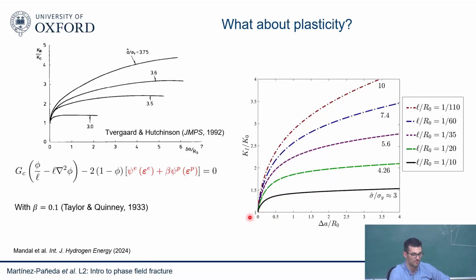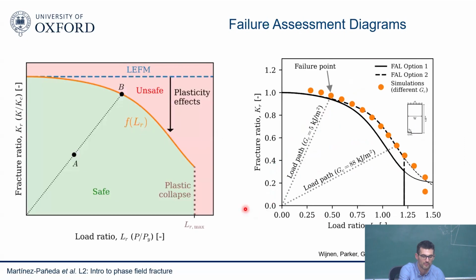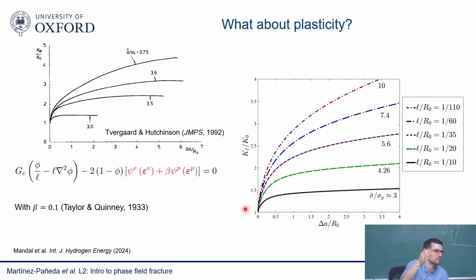Cracking starts always at the same place. You know your fracture toughness. So the only thing that you don't know is how much plastic dissipation you have. And that will depend, of course, on your yield stress and your strain hardening exponent, but those things you know from a uniaxial stress-strain curve, and your local fracture toughness, which you can calibrate with this. So that's another option. And then you know that you're dissipating the right amount of plasticity. In this case, this is some sort of a normalization, fracture process zone length.